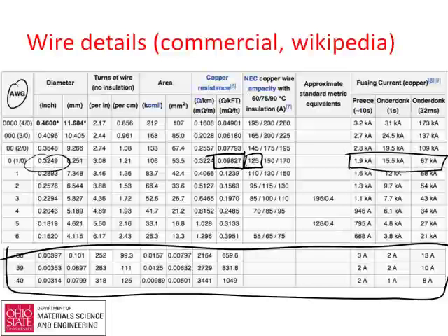And these are the 40 gauge wire. You can buy from McMaster-Carr, get a spool fairly cheap. This has a diameter of about 70 to 80 microns, so you can easily break it. Again, we can use that for strength testing. It has a cross-sectional area of 0.005 millimeters squared. And this has interesting resistance.